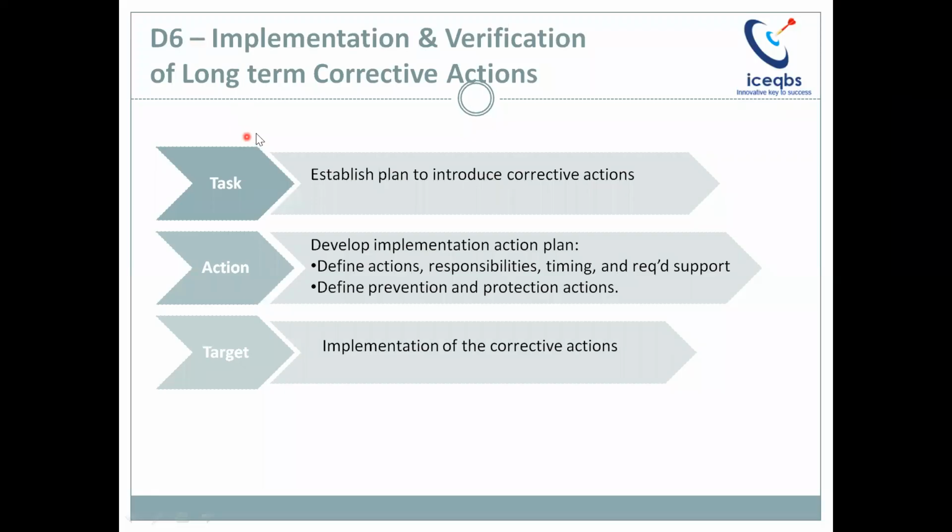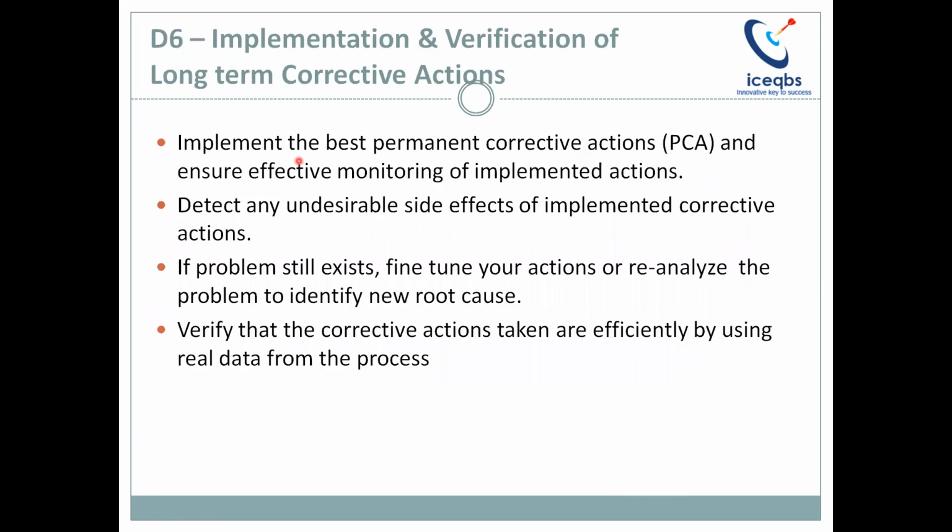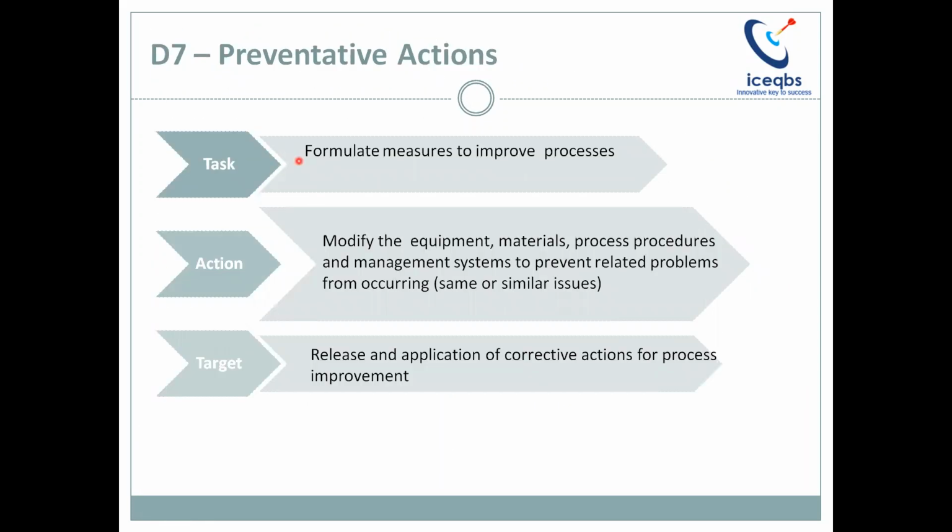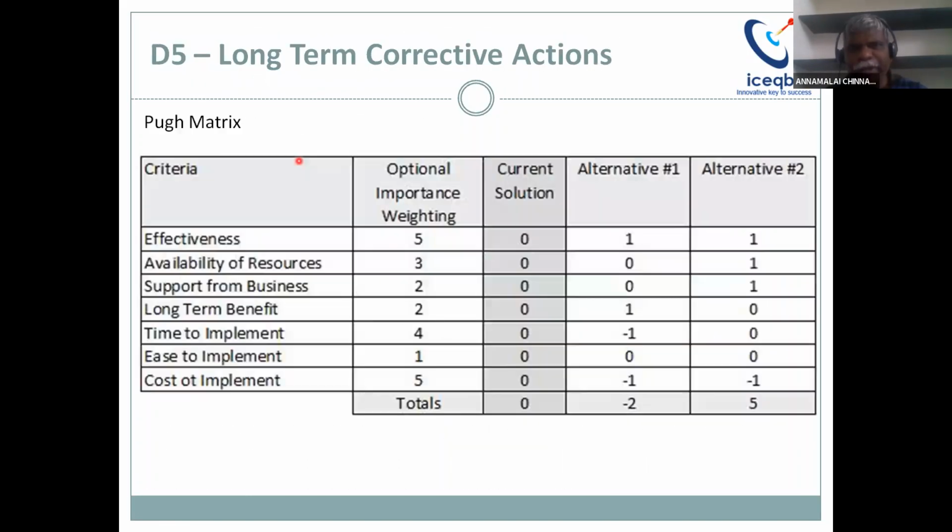The Pugh matrix, is it a manual document, just like a sheet we have to fill in or mark? Yeah, it is only a small template, right? You just prepare a small template like this. You list down the criteria you are going to use for evaluating the solution, and then you can use this simple template.